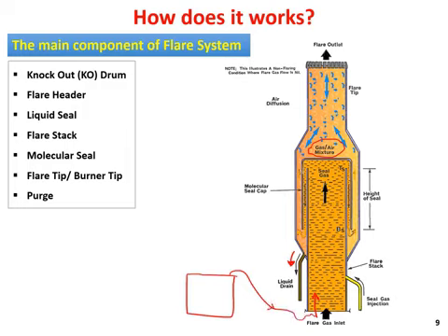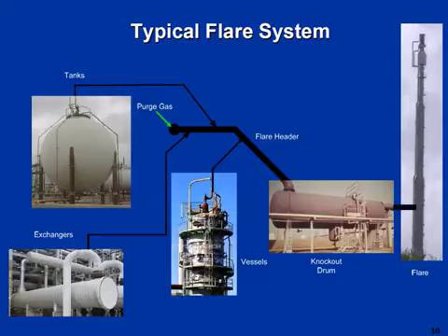So this gas might have some liquid, and this liquid can go through the flare with this gas. So we can collect that liquid by using this liquid drain. Or for the sealed gas injection, we might use steam, and that steam might condense. So it creates some liquid that we have to collect. We are talking about this part here.